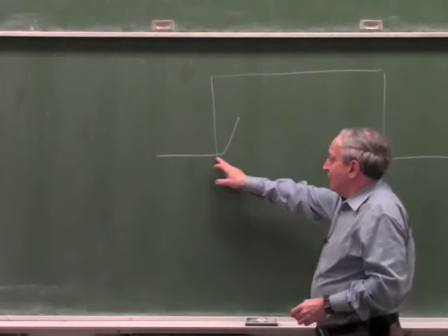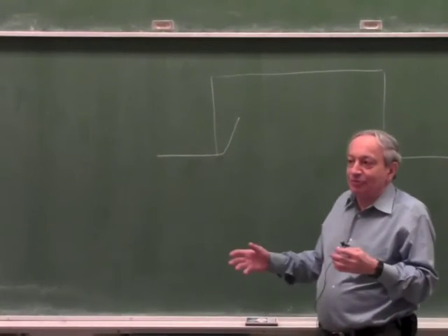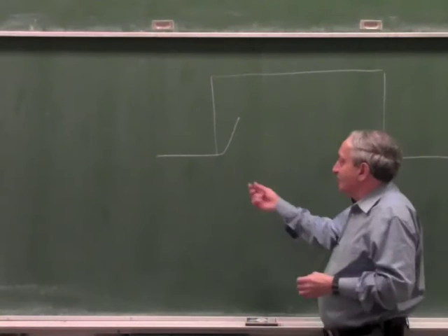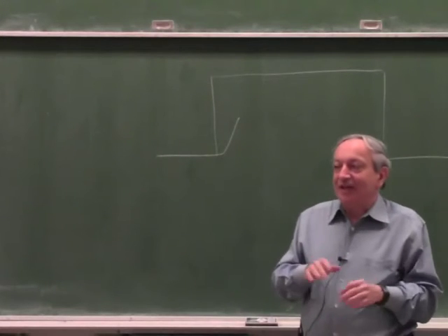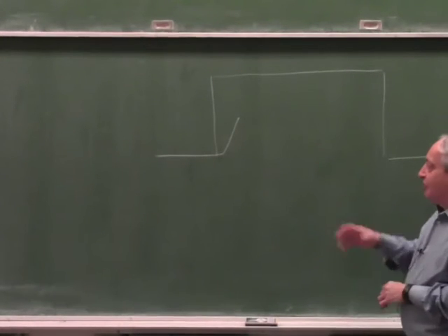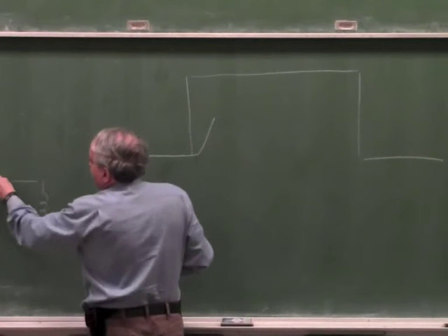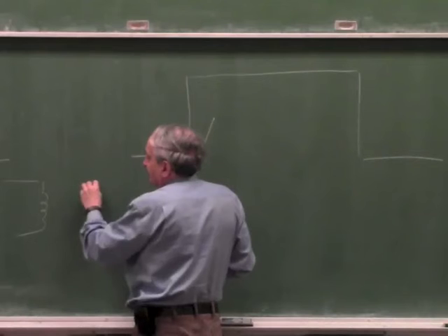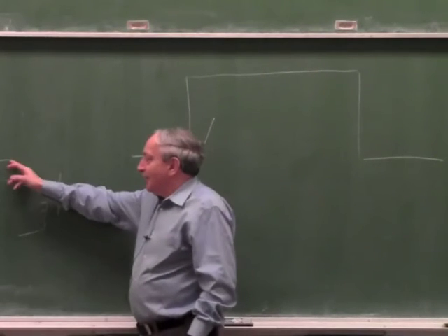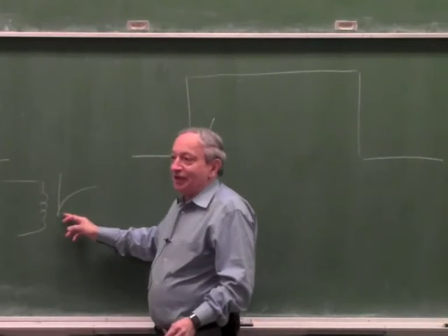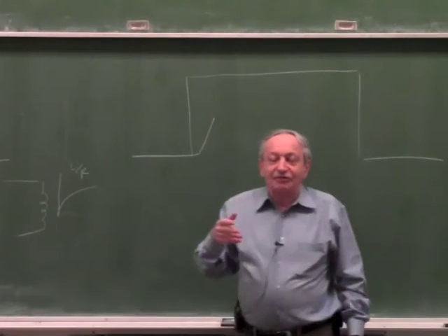So let's start with this corner. Why would there be a little bit of a delay? When you give a servo a command and you look at an output, like at a motor or a solenoid, there's always a little bit of delay. Okay, so there are a few reasons for that delay. The first reason is electrical. If you're talking about an electromechanical actuator, when you give it the command, say the current jumps, nothing happens because of something you all know, there's a time constant, okay? So just because you gave it a command, even before inertia, it takes a time constant, say L over R, until the current really is strong enough to do a lot.